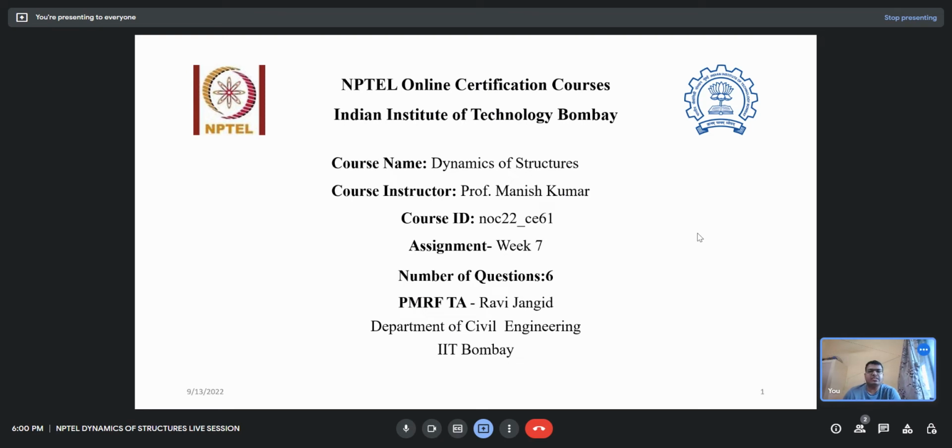This is the live session for week 7, in which we will discuss 6 questions. And in this, we will focus mainly on the lumped mass system and the continuous mass system, like the equivalent single degree of freedom system. In reality, if we have a 3 story or 4 story building, how do we convert it into the lumped mass system, or consider it as a continuous system? For this, we will solve some examples.